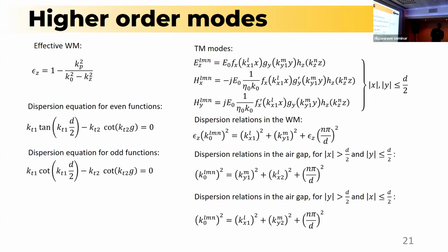And it will depend on the dependence of the field along every direction. If it is an even function, we use this dispersion equation. And if it is an odd function, we use this dispersion equation. So this is basically the higher order modes. It's the same idea as the fundamental mode with some extra details, including these coefficients L, M, and N, accounting for more variations of our electromagnetic field inside the cavities.